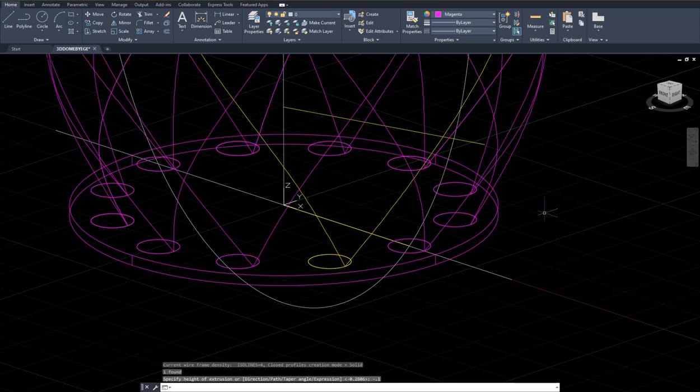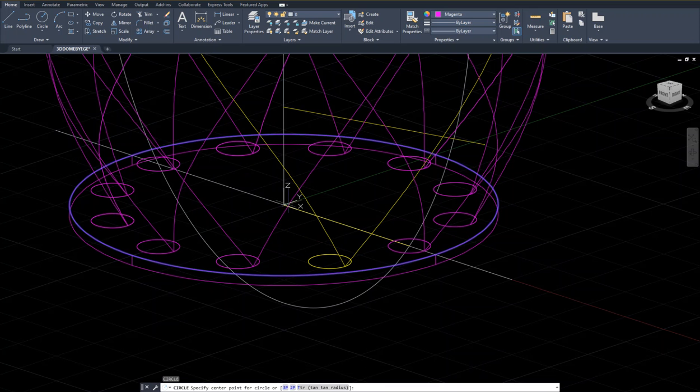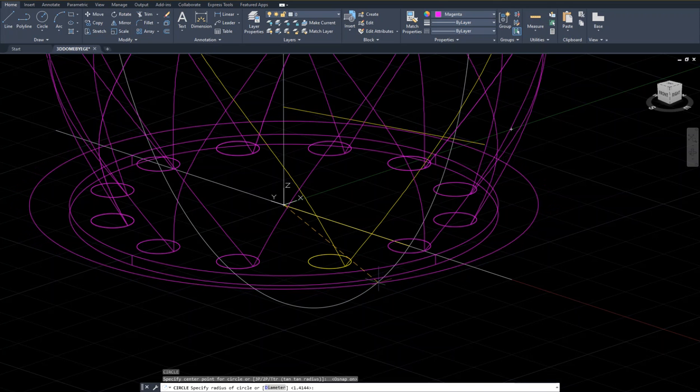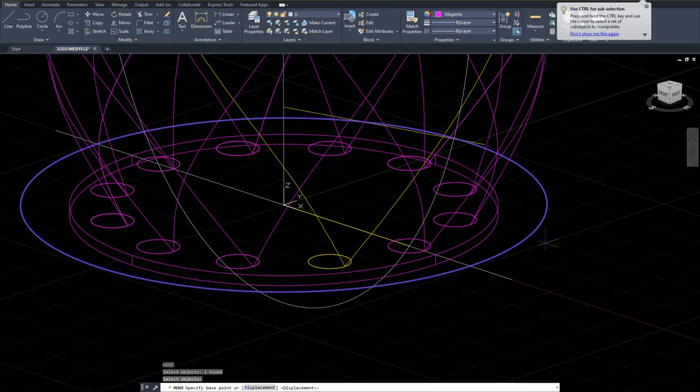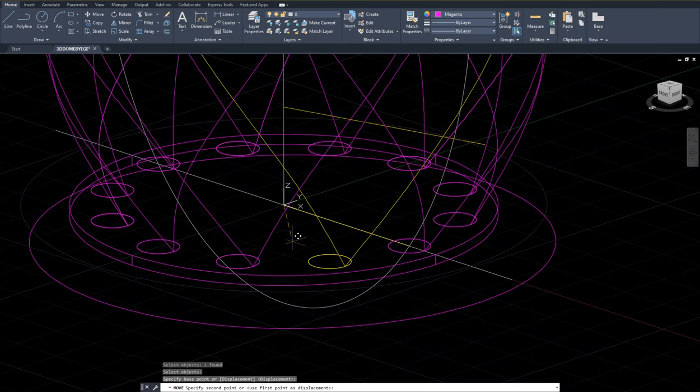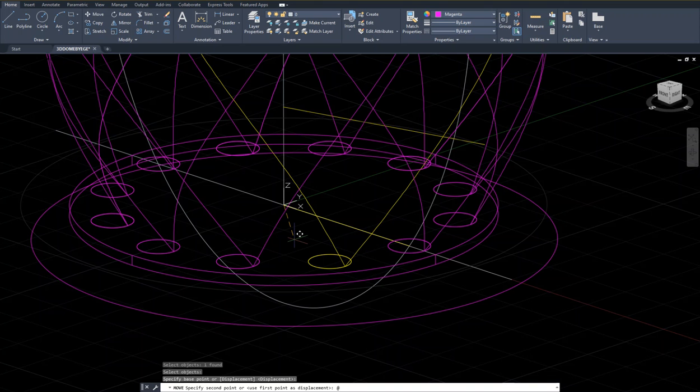Okay. And yeah, well, pedestal, not necessarily panel, but pedestal. So let's make another copy of this. Okay? So circle again, and let's draw a second circle starting from 0,0. This we need object snap for. Okay, click and make it slightly larger than the previous one. Okay, and I'm going to move this down. Click, enter, from where it is below. So we're talking about 0,0, minus 0.1. Okay, only we're moving to a point below.